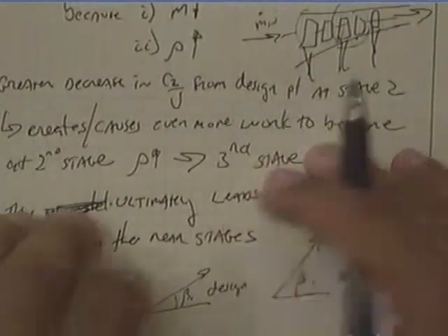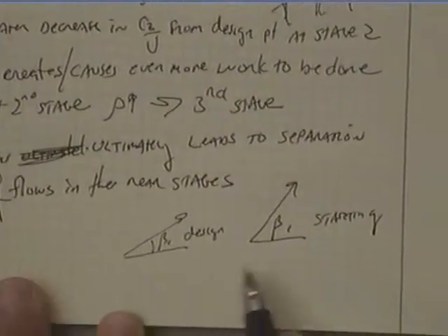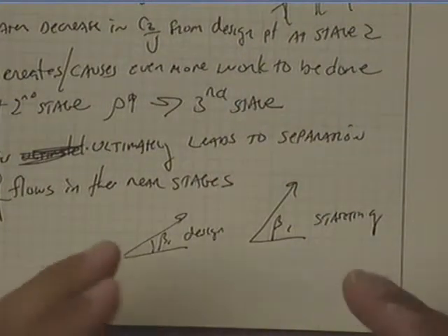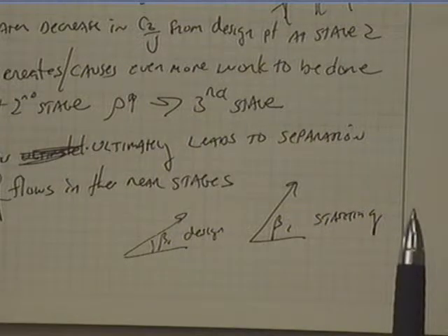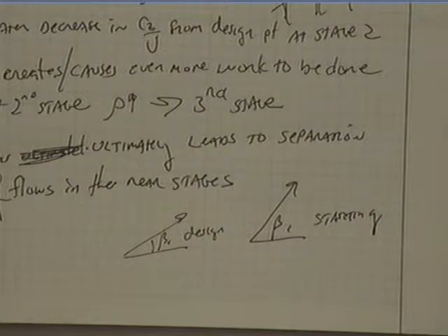In fact, this could lead to a significant problem in that you're literally closing down the flow area more than the actual geometric area, and the back of the axial compressor will start acting as a throttle, okay, as you're trying to start up this axial compressor. Okay, so this is what's known as the starting problem for an axial compressor.